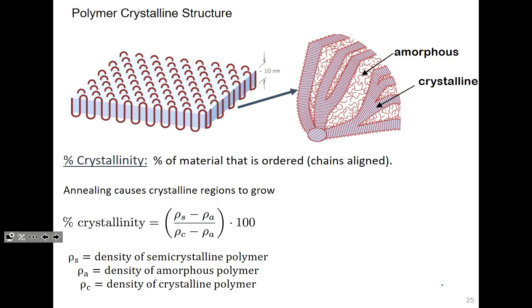You will have some areas that are crystalline, and when they do that, it looks sort of like this, where you can see these hairpin turns that I'm outlining in green over the red. You can see that they'll go back and forth like this. So that's how they pack when they're crystalline. That's called a crystalline area or a lamellae. And those lamellae structures can also be connected all in the same chain, but have some amorphous regions as well. So the structure that you often see is what's shown on the right here, where you have areas of crystallinity surrounded by amorphous chains that I'm circling here.